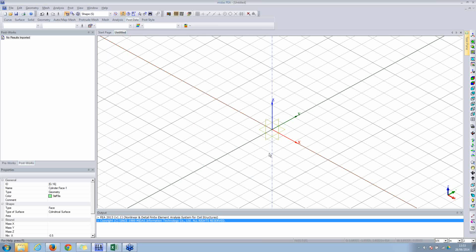But if we want to look at the overall effect, that is the rebars in transverse direction, placement of the rebars, if you want to capture the whole 3D effect, okay, add shear links in the beams and all those things, then we need to go for solid modeling. Yes, that is the only difference. One is a 3D approach and one is a 2D approach. Both are fine. It depends on how detailed you want to go for the analysis. Both have their own pros and cons.